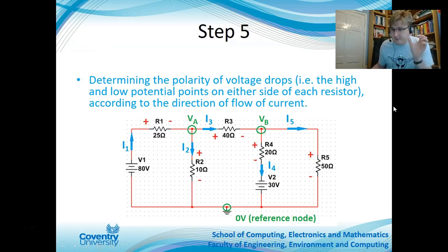So from a circuit analysis perspective, using nodal analysis, because it only gives you 2 simultaneous equations, makes it a mathematically simpler solution. So sometimes when you're considering mesh or nodal analysis, look at how many unknowns it will give you and choose the one with the least unknowns, because that will make the maths easier, which also reduces the chance of any mathematical errors being introduced in your calculations.